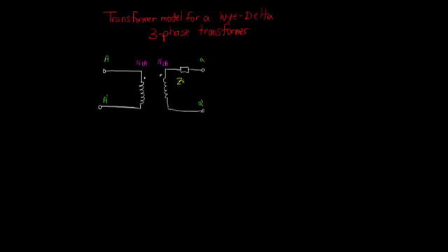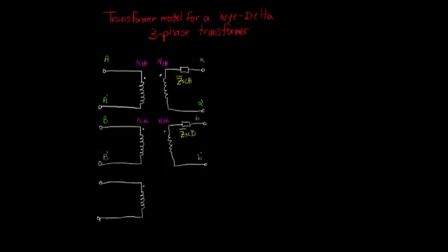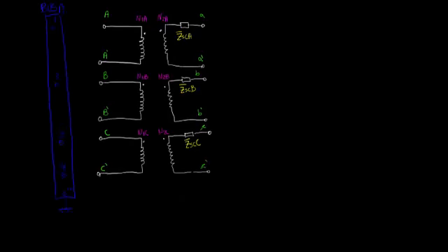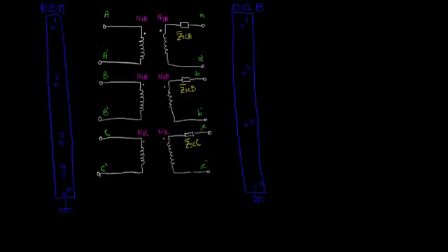Now, let's talk about a three-phase transformer in a Y ungrounded delta connection. This transformer is built by considering three separate single-phase transformers in which their nodes are connected according to the three-phase connection. In the first terminal, nodes A, B, and C should be connected to three different nodes, for example, nodes 1, 2, and 3 of bus A, respectively. And for a Y ungrounded connection, nodes A', B', and C' should be connected to each other to an isolated node of bus A, for example, node 4.